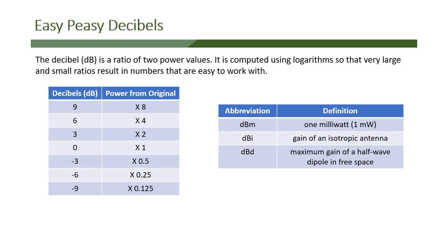You might see, for example, some antennas like a vertical antenna that's ground mounted may have a negative dB compared to a half-wave dipole in free space. So that's also possible, that you will have an antenna that's not as good as the dBd reference antenna.